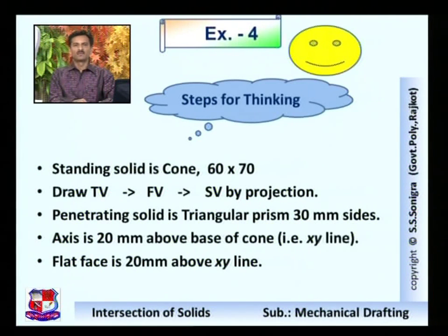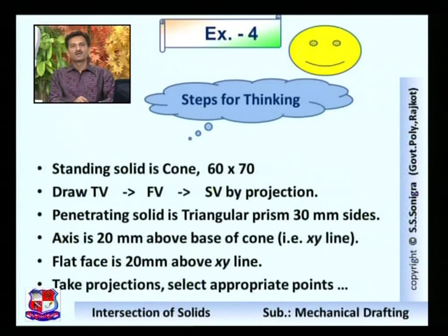Two cases would be there. One case is the axis is 20 mm above the base, and another case is flat face is 20 mm above the base, that is XY line. So both the problems would be different. So here we will consider the flat face is 20 mm above the XY line. Take projections, select appropriate points.